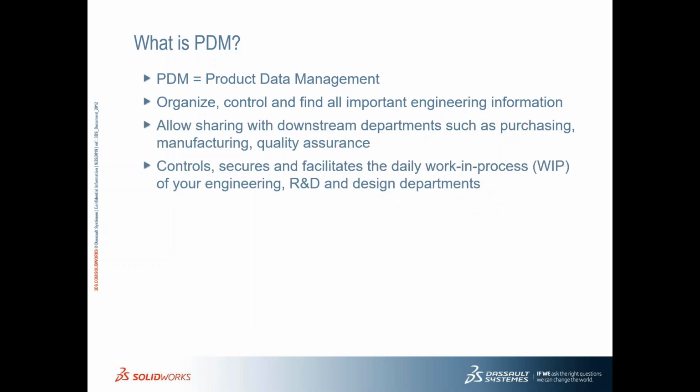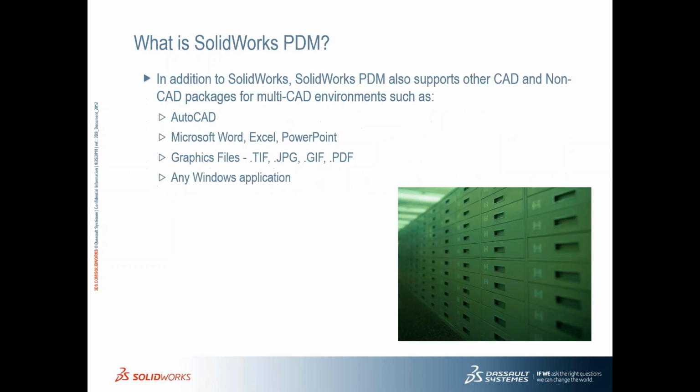The benefit of PDM is that you can share your data amongst departments and amongst the technical people that are creating this data. On top of that, unlike putting files in a normal Windows Explorer environment where we don't have complete control and security over those files, PDM gives us the ability to control and secure our files through what we call a workflow. That way we can track our content as we're creating it and as we're releasing it to the people that need it.